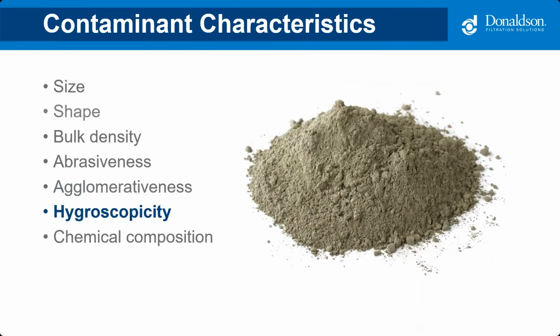Hygroscopicity, that's a mouthful by the way, is the dust characteristic that will readily take up and retain moisture. Hygroscopic dust examples include acid, starch, and cement. Selecting the right collector and filters is important for dust that retains moisture. There's potential for plugging up filter media.